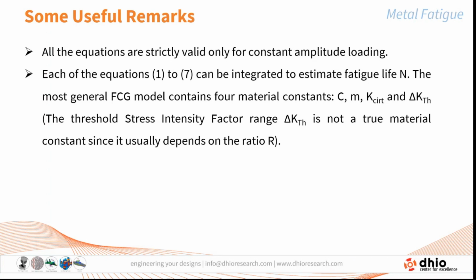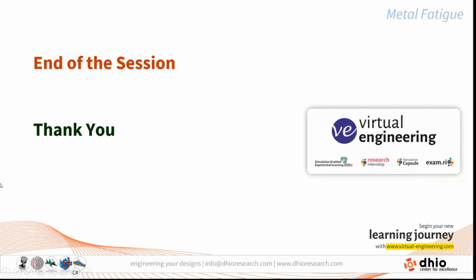So the threshold stress intensity factor range is again going to be another important factor in predicting the fatigue life of the component by using the fracture mechanics approach. And it also depends on the ratio of the stress intensity factors, that is K minimum to K maximum.